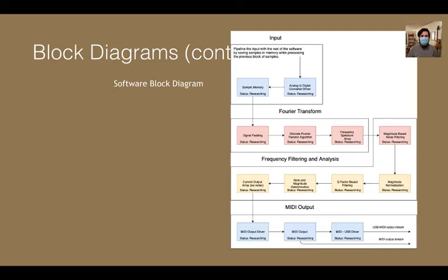So from there, we detect the notes via a scaling threshold that scales based on the RMS of the input signal, because we found that the thresholds were not static as the note sustained and the volume of the note you played changes. And we kept a 6-note output array, which at all times holds up to 6 notes, which is used by our MIDI output driver.